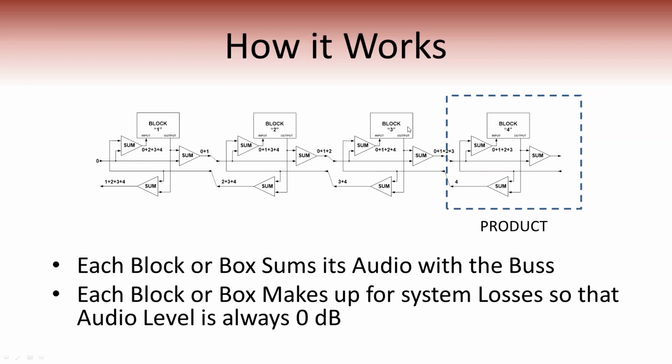My output, likewise, can be selected as to what is sent out to the rest of the network. There's jumpers in these lines that allow me to selectively send either upstream or downstream to the rest of the bus what's coming out of my block.